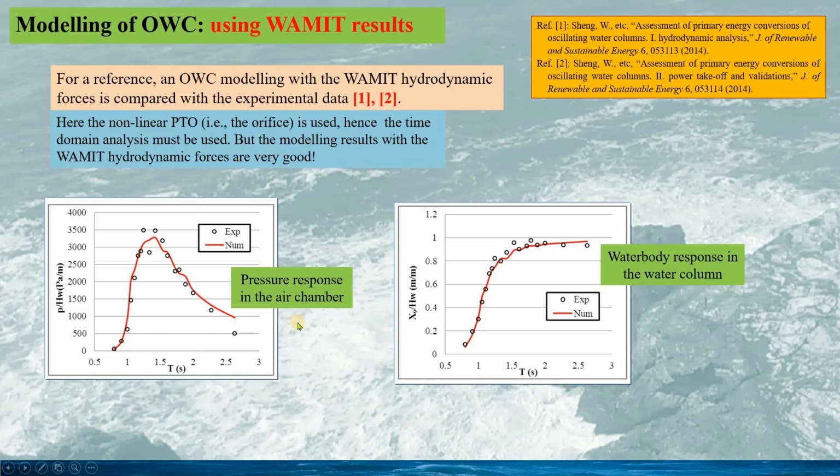Hence again, from this example, we can see WAMIT gave reasonable hydrodynamic parameters for this fixed OWC device, while NEMOH wrongly predicts the resonance frequency of the internal water body motion, the piston. This confirms the warning from the NEMOH developer: NEMOH might not work in OWC modeling.